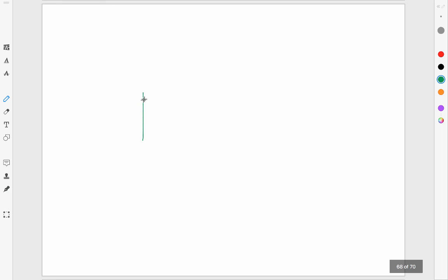Okay, so let's imagine this was my flip-flop. This is a base flip-flop, the smallest entity that you can imagine, and of course it will have positive hold time and setup time, because that's how flip-flops behave. So if I look at just this one, then T sub h and T sub s are going to be greater than 0. So if that's the flip-flop you were getting, things would be fine.